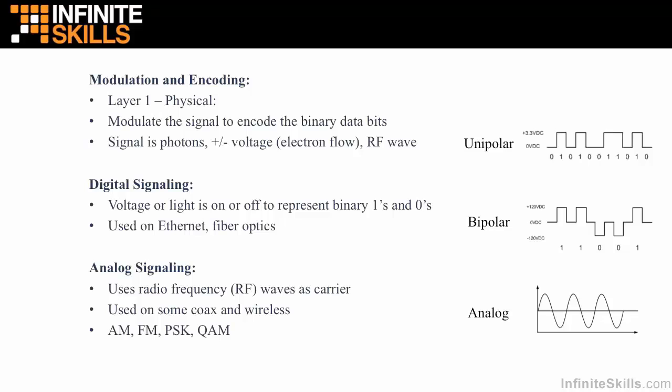And then we drop to minus 120 volts to represent binary 0s. So this is bipolar digital signaling. And again, this is just one example of the many forms of bipolar digital signaling that can exist. But this example is roughly out of the T1 era of signaling over long distances. So we use much greater voltages so I can afford a lot greater attenuation because my data runs are so much longer.